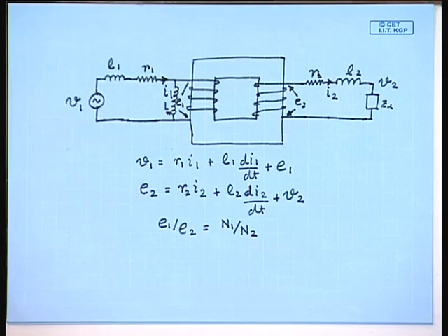This is so because the induced voltage E1 leads the flux by 90 degree. So, the current flowing through the inductance connected across E1 will lag E1 by 90 degree and will be in phase with the core flux phi m, which is responsible for generating the core flux phi m. So, the effect of finite permeability of a practical single phase transformer is taken care of by considering a magnetizing inductance across the winding and leakage inductance in series with the winding.